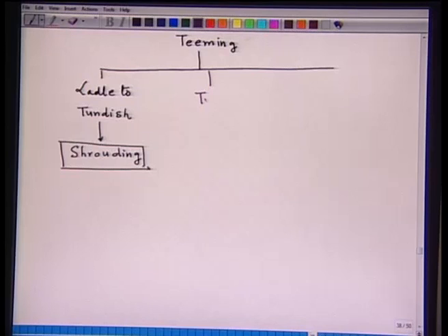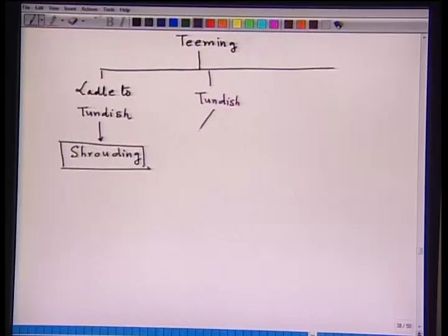So, accordingly, the tun dish can also contribute to a large number of inclusions if proper control is not being done. What is the proper control? Say first, the steel is in contact with the wall, so refractory wall is a source.